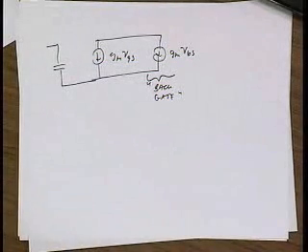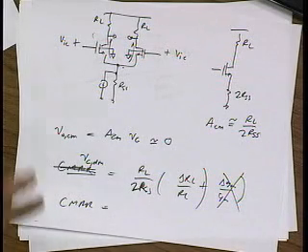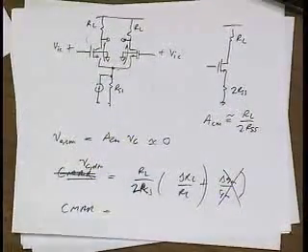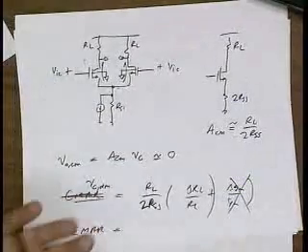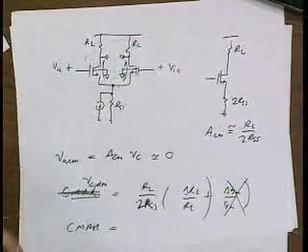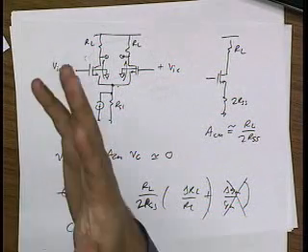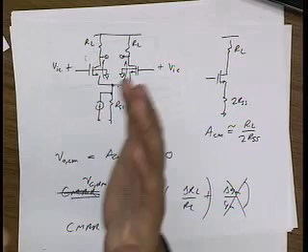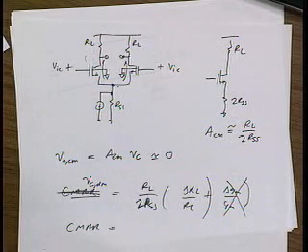Oh, yes, question. Connect the body to the source. Okay, why can't we do that? Well, sometimes we can, but only in a triple well process. Usually for the NMOS you don't have that option. So you might wonder, why would somebody use a PMOS input stage when, in fact, an NMOS transistor is better? You see a lot of op-amps with PMOS input stages. Who can give me 3 reasons why I would use a PMOS input stage? One you all should know by now. Okay, one is body effect. I can tie the source to the body and I get rid of that body effect.